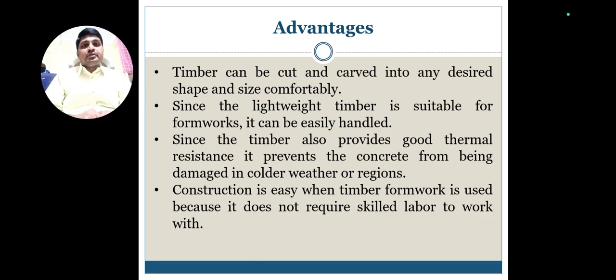Coming to the advantages of timber formwork, it can be made comfortably in the desired shape and desired size, it is light in weight, timber is suitable for formwork, and it can be easily handled also.